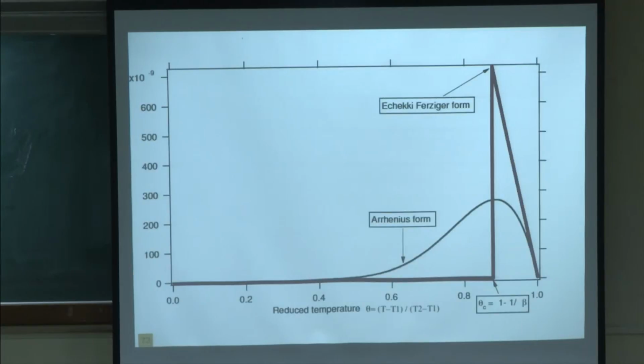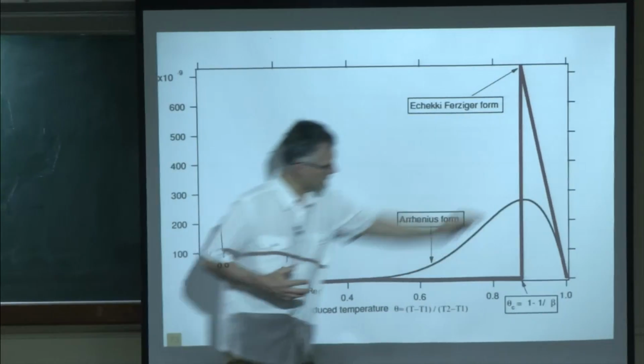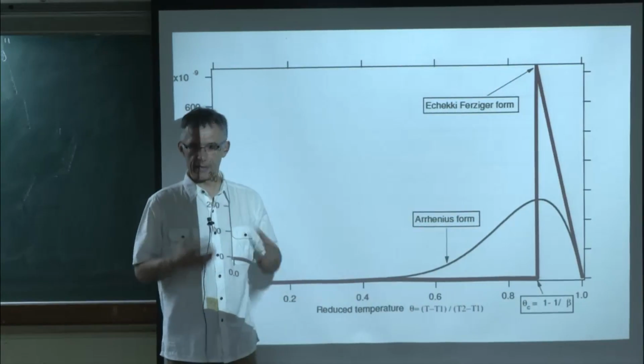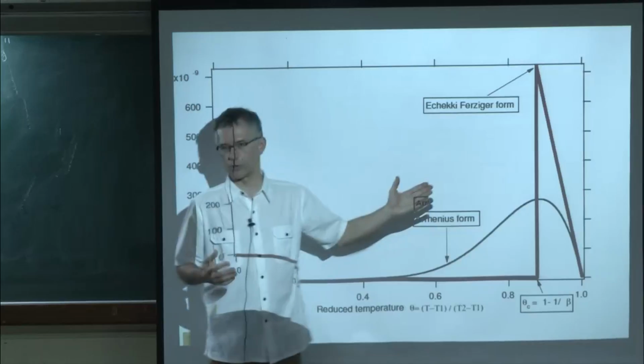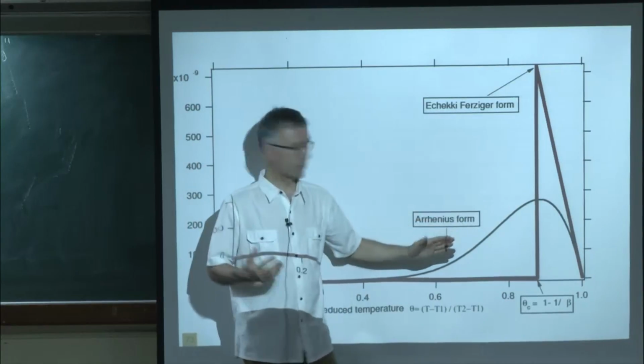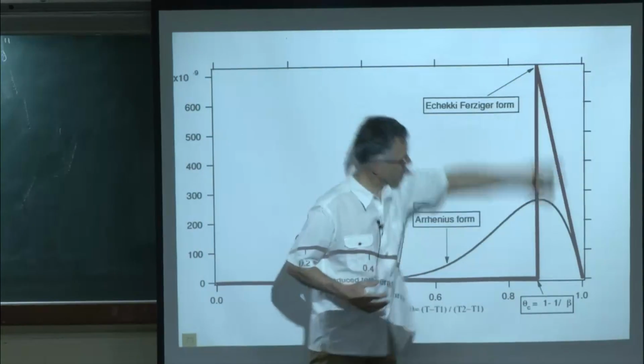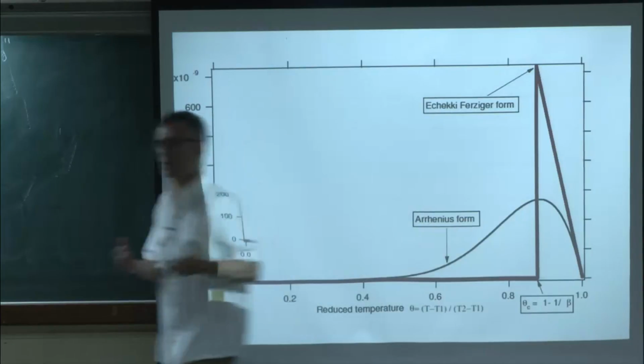He said, what is important about the physics of this problem is not the exponential shape here. It's the fact that nothing burns and then everything burns. So let us replace this exponential shape for the heat release by a straight line up to this point and then a straight line here.